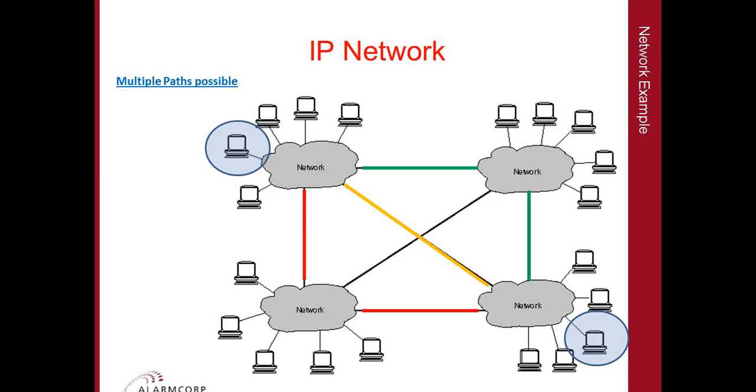Now, the key point here is that the various packets can get redirected over the various paths on a dynamic basis. Most switches do try and do some sort of load balancing, and unless this is managed and factored into the video system design, we can end up with video packets arriving at the destination out of sequence.